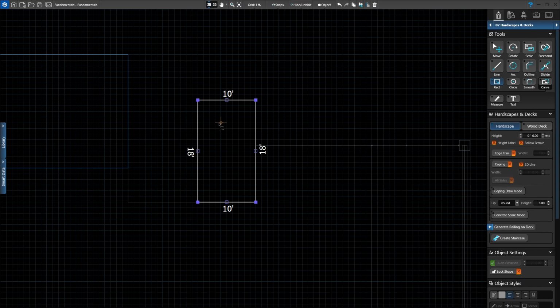So I'm going to show you how to create these hardscape handrails that have a curved edge to them. And I'm going to teach you how to copy and paste because they're mirrored on both sides of the end of the walkway. So we'll start with the line tool and then we'll switch to the arc tool. Go over to your toolbar and left click on your line tool. We're going to go to the top right hand corner of the hardscape entryway. Left click and come up 4 feet.